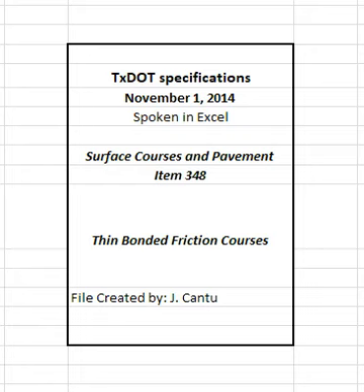Schedule and participate in a mandatory pre-paving meeting with the engineer on or before the first day of paving unless otherwise shown on the plans. 4.1 Certification. Personnel certified by the department-approved hot mix asphalt certification program must conduct all mixture designs, sampling, and testing in accordance with Table 6.